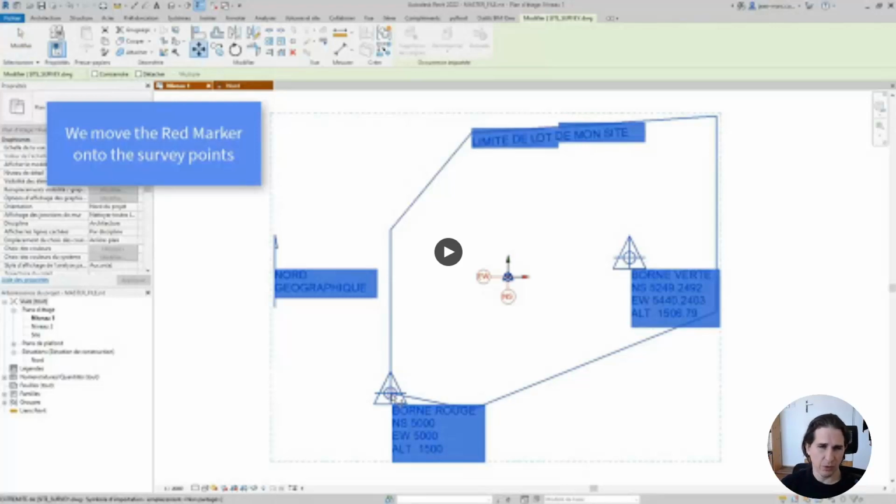Very often you would have large coordinates on the CAD file, and that would probably be a problem. So the center to center insertion will allow you to put the DWG positioned not far from the project base point. Also, the second point would be to pay attention to units. Always specify them. Don't use automatic. It rarely works in Revit.